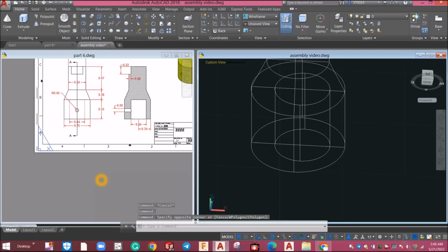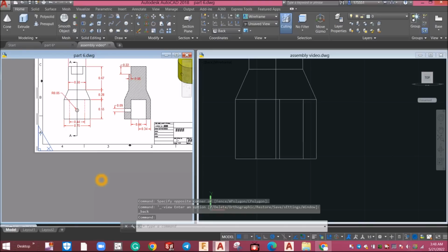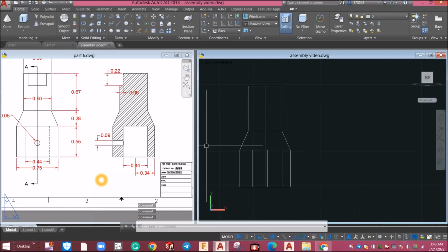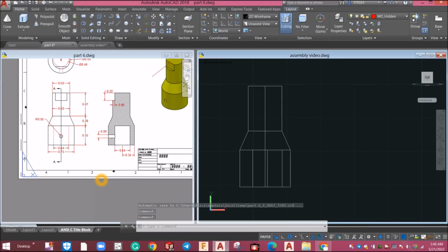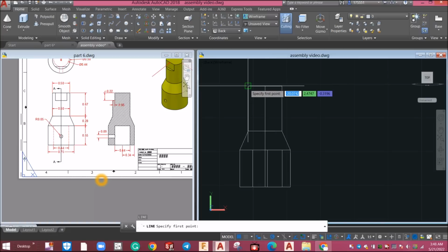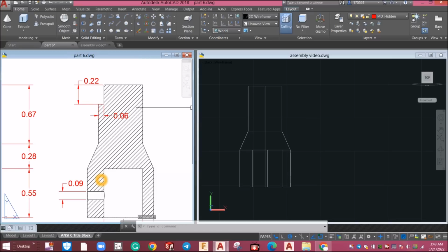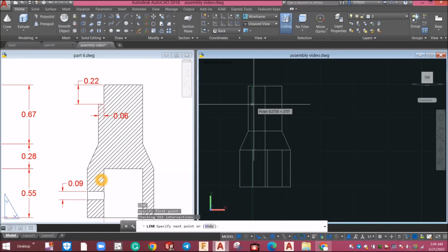So we're good. All right. Now I'm gonna bring this to back view, which is this one here, and I'm gonna chip off this portion here. So I'm gonna draw a line from quadrant, move it to your right for 0.06, which is this one here, and the height is 0.22. So line again from that in point and enter 0.22.